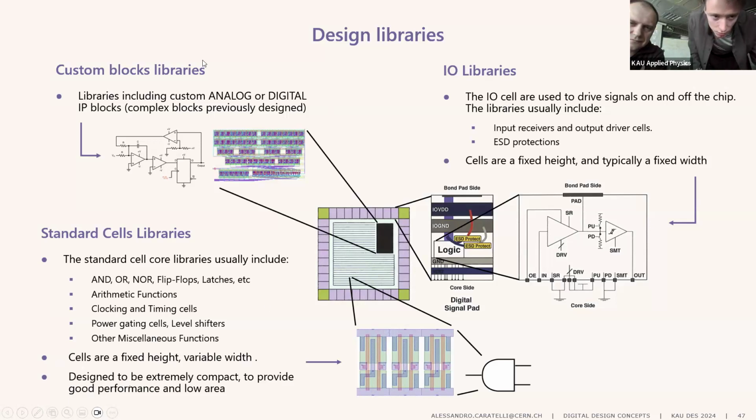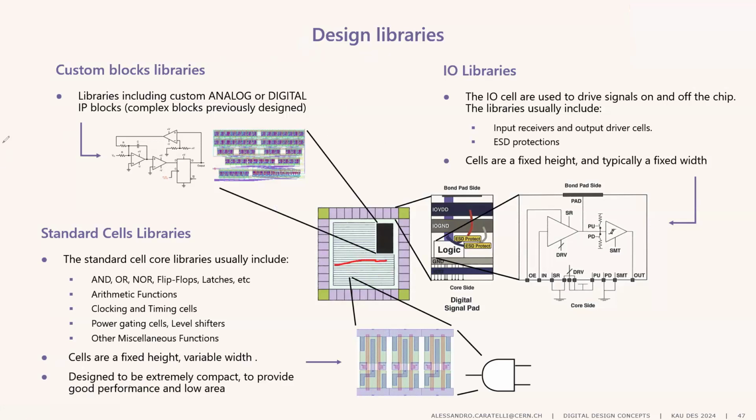Is this an FPGA that is shown here, or is this an ASIC? This is an ASIC. It's an example for an ASIC. On an FPGA you don't have this, in the sense that in the FPGA, this job is already done. Somebody already did the physical implementation of the FPGA, and you are basically connecting logic elements to create the circuitry, but it's already drawn.